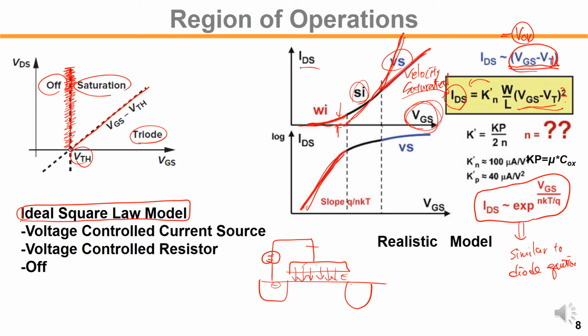The electron was supposed to move from source to drain freely, but because of the higher and higher field, the electron cannot move as fast because it is bumping onto the surface, and the current flow is hindered by this strong electrical field, so the current is saturated.